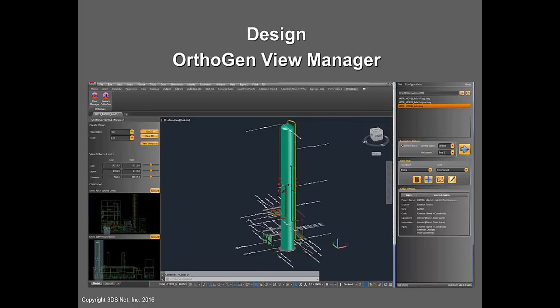Here's a screenshot of the View Manager. We load our form. It shows us our current orientation and scale, our current clipping. We can key in volumes in this clip. We've got key plans here that we can just window volumes in the plan and in the north. Once you've got a volume defined, you can use these sliders to just step it along. You can step down the rack, step and save, create your rack plans. And you can see the 3D annotations out here.